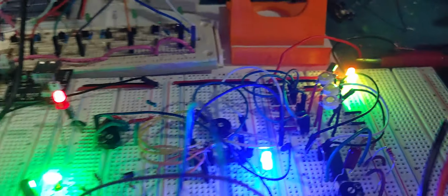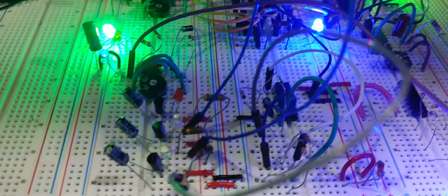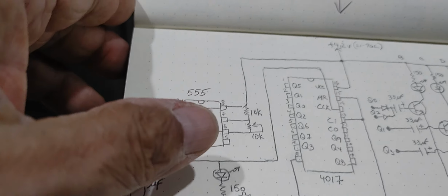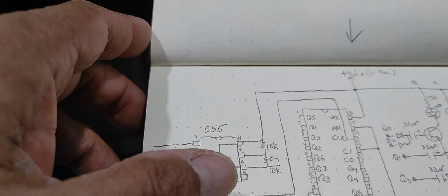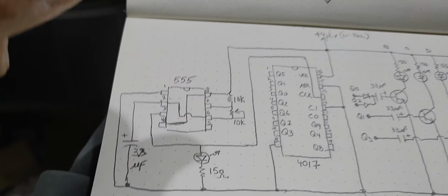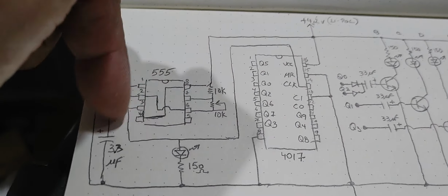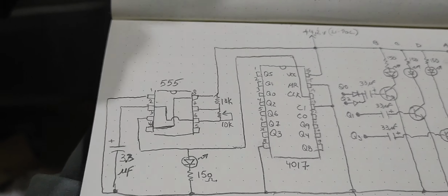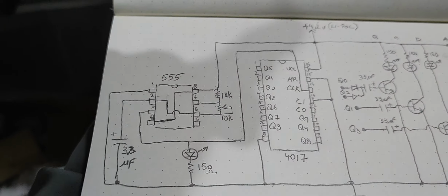The other circuits that I've been showing here, I'm using a 4060 counter, a binary counter, and that counter has an internal oscillator, so you don't need this circuit here. All you need with the 4060 is a capacitor and a couple of resistors to establish the timing, the clock pulsing, so you don't need these bulky components here. Like I said, I could use surface-mounted components to keep the circuits very compact, or programming a chip would be a lot more compact.